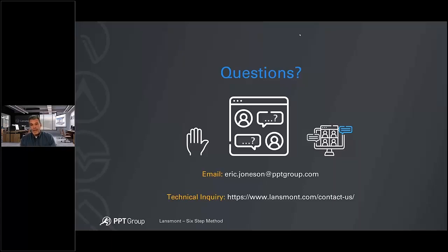We calibrate that in the lab by putting it through a series of dynamic events, drops or shock inputs, so that we can measure the response of that system. So we know what we're putting into it: controlled inputs, drops, shock pulses. We measure the response of the decoy or the instrumented item, and then we send that out into the field. We get responses from the field. We can then back calculate, so to speak, what comparable energy was associated with those events.